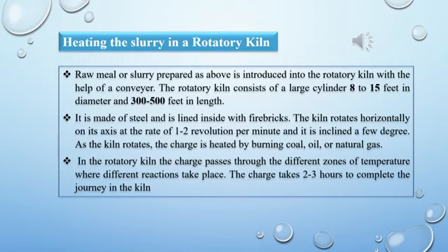Now the second point is, it is made of steel and lined inside with fire bricks. The kiln rotates horizontally on its axis at the rate of 1 to 2 revolutions per minute, and it is inclined a few degrees. As the kiln rotates, the charge is heated by burning coal, oil or natural gas.